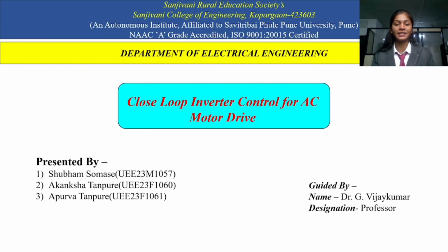The topic of our presentation is closed loop inverter control using vector control under the guidance of Dr. G. Vijay Kumar sir. Closed loop inverter control using vector control is a modern technique used to run AC motors with high performance. In this method, the inverter supplies the motor and the sensor continuously measures motor speed and current. The feedback signals are compared with the reference value and the controller adjusts the inverter output to maintain accurate speed, torque and flux. Further slides are explained by Akansha.